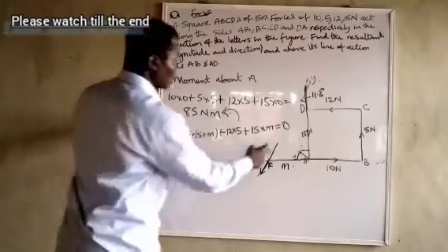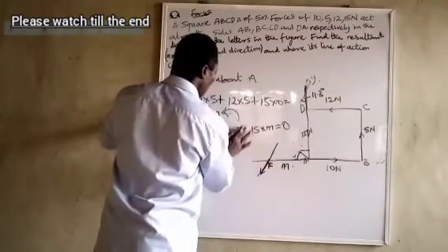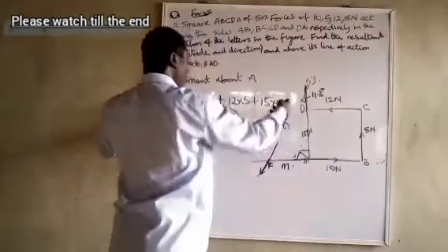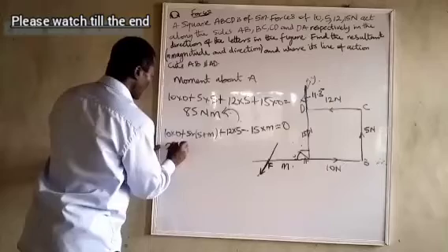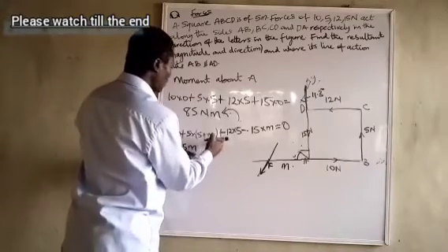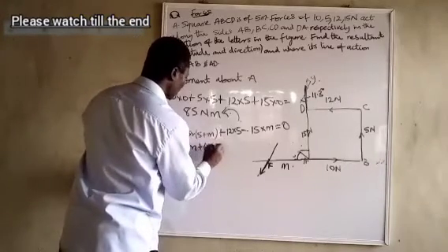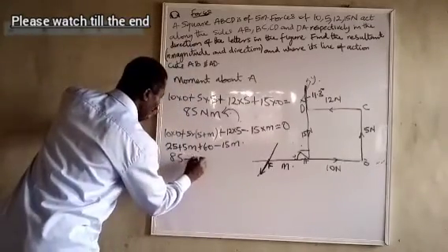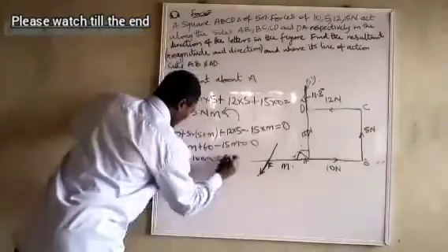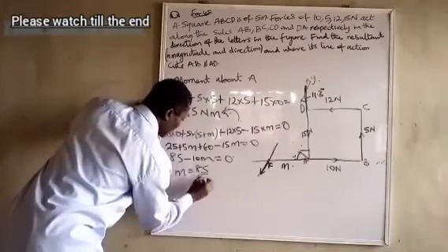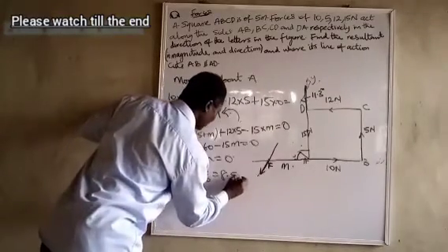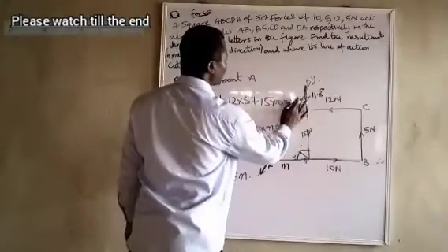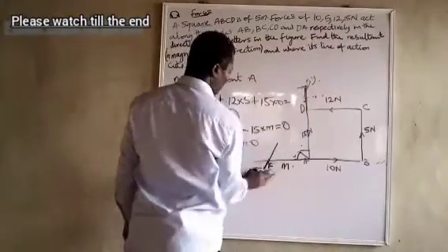At the end of the day, we are going to have 25. Okay, wait. This one is downward, please. This one is going to give us minus. This one is positive. This one is downward. So this is 25 plus 5n plus 60 minus 15n. So I can see that 85 minus 10n is equal to 0. So n will be equal to 85 over 10, which is 8.5 meters.